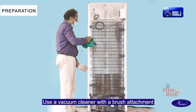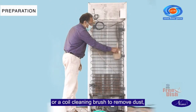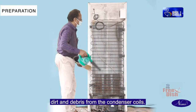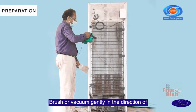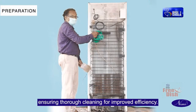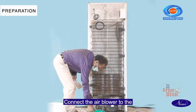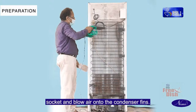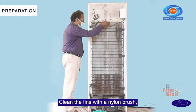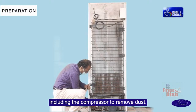Use a vacuum cleaner with a brush attachment or a coil cleaning brush to remove dust, dirt, and debris from the condenser coils. Brush or vacuum gently in the direction of the coils to prevent damage, ensuring thorough cleaning for improved efficiency. Connect the air blower to the socket and blow air onto the condenser fins. Clean the fins with a nylon brush, including the compressor, to remove dust.